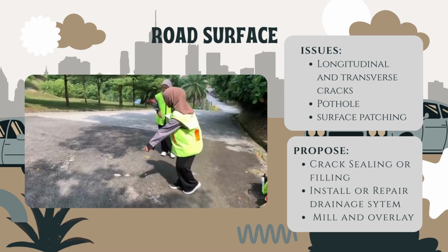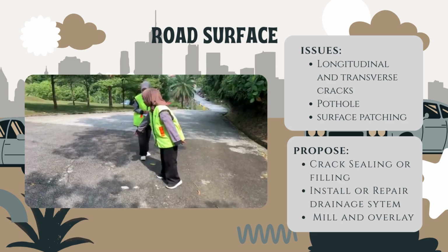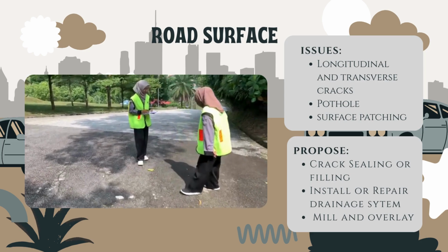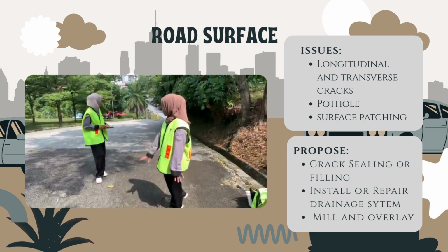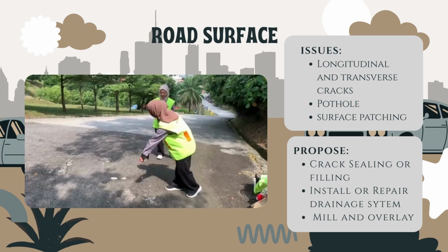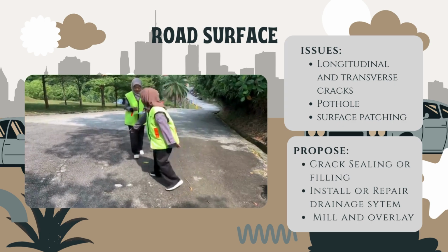The last issue is that there are previous patchworks on the road surface that are uneven, which results in an irregular and unsafe road surface. It is recommended to remove the damaged top layer and overlay with a new one using proper compaction and mix design.